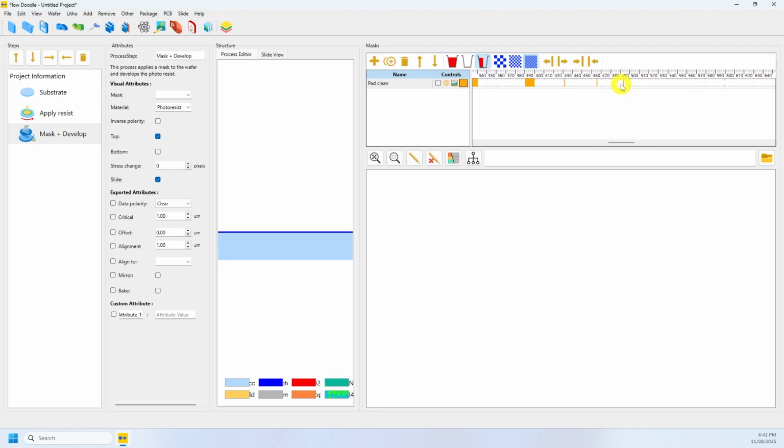You can also choose between Set Mask Pixels Dark, Set Mask Pixels Clear, or Toggle Mask Pixel Polarity to control how mouse clicks affect the mask. Click the mask area to turn pixels dark or clear and create your structure.